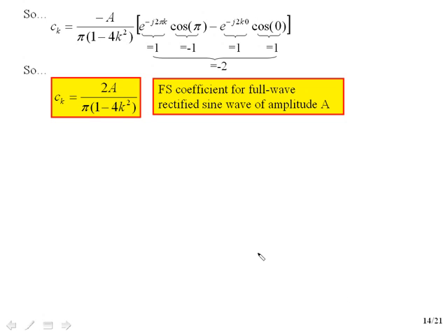Okay, so now we're evaluating at pi and 0. Here is that term evaluated at pi and evaluated at 0, and these are very simple evaluations. E to the minus j 2 pi k. Well, I've got an integer times 2 pi sitting up in a complex exponential. It's telling me that it's integer multiples of 2 pi. So 0 times 2 pi, 1 times 2 pi, 3 times 2 pi, they all put me at the same place on the complex plane. Where are they putting me? Here's the real part.